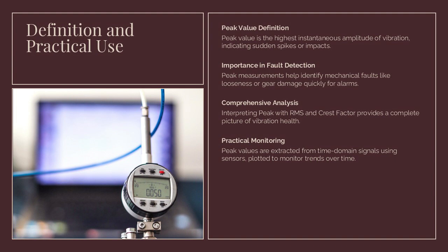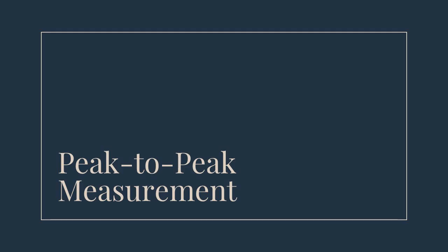However, relying solely on peak can be misleading since it does not account for overall energy or sustained vibration levels. Analysts should interpret peak alongside RMS and crest factor for a comprehensive view. In practice, peak values are extracted from time-domain signals using sensors and data acquisition systems, and plotted to monitor trends over time.